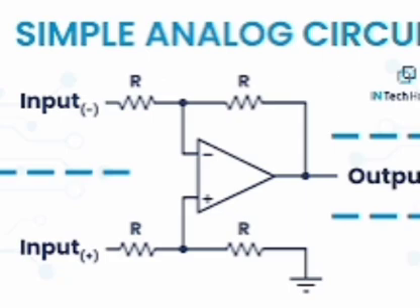Half wave rectifier. Average value of current and voltage. Ideal case: IDC equal to IM by pi, IM equal to VM by RL, and VDC equal to VM by pi. IDC means average value of current, VDC means average value of voltage, IM means maximum value of current, VM means maximum value of voltage, RL means load resistance. Practical case: IDC equal to IM dash by pi, VDC equal to VM dash by pi, IM dash equal to VM by RS plus RF plus RL, numerator part VM, denominator part RS plus RF plus RL. VM dash equal to IM dash into RL, where RS means coil resistance, RF means diode forward resistance, RL means load resistance.